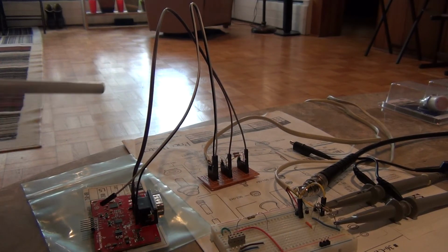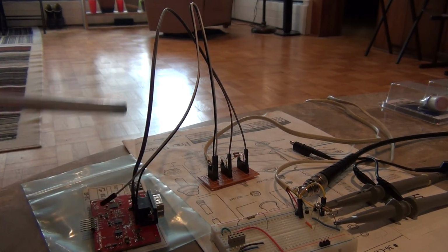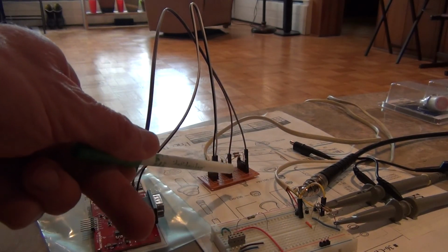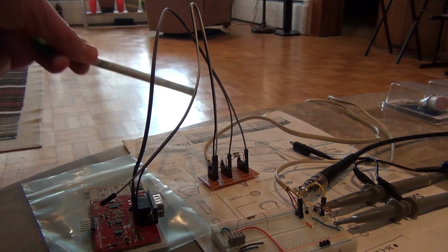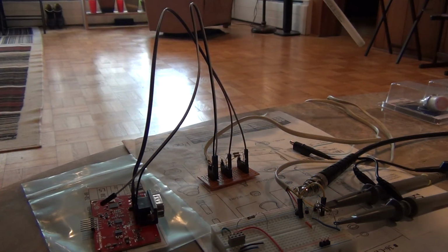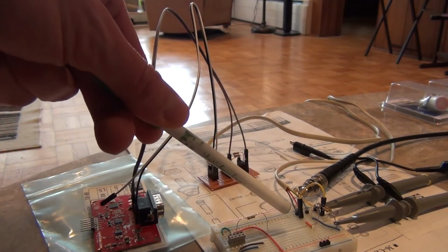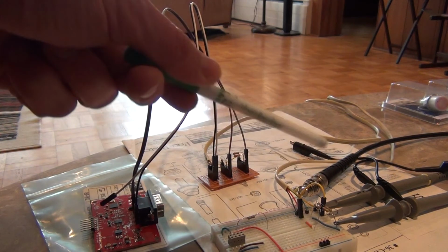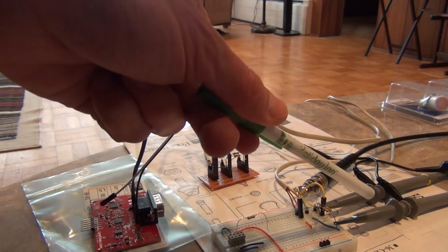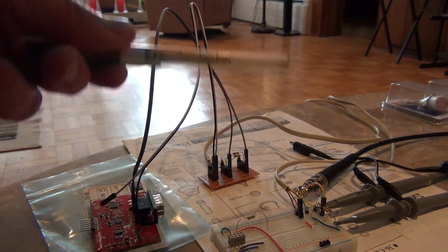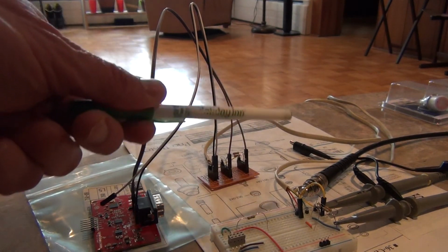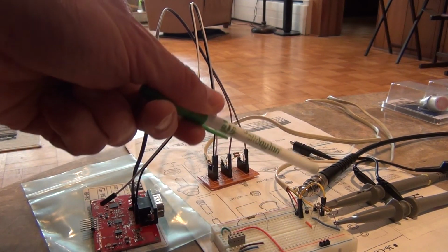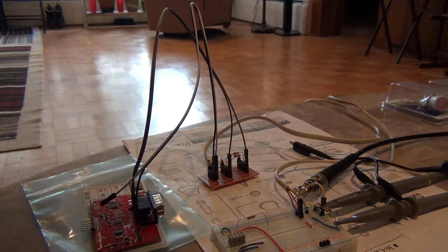Okay, here is the setup. I have an unpowered CAN bus driver that is connected to this small PCB that has a terminating resistor between the CAN high and CAN low, and then those wires snake around and go for a few meters until they return back to this breadboard, which has another terminating resistor, and there is a channel A and channel B of PicoScope connected across it. There is also a 470 ohm resistor connecting CAN low to the ground, and finally there is an AWG supplying 1 volt to CAN high. Now let's power up the PicoScope and see what happens on the screen.